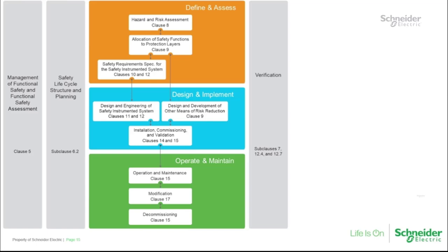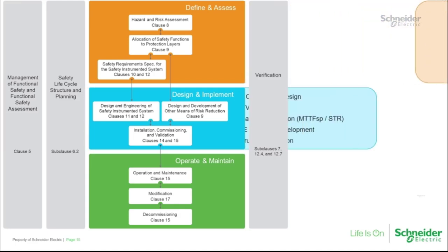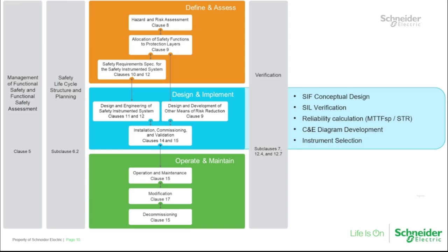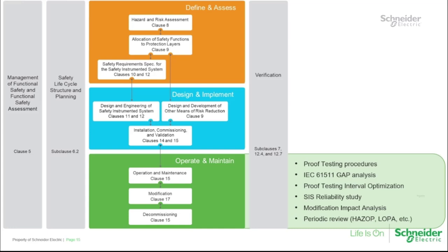The IEC 61511 standard requirement is represented by the safety life cycle. Over the years, we have helped many customers in implementing these activities of the safety life cycle and meeting the requirement of the standard by doing HAZOP studies, quantitative risk assessments, SIL determination using LOPA methodology, creating the safety requirement specifications, or helping in the design of the safety instrumented functions, doing SIL verification activities, also doing proof test procedures, proof test interval optimization studies, periodic review of the HAZOP, of the LOPA studies,